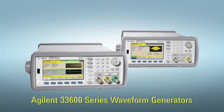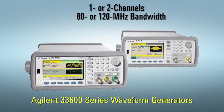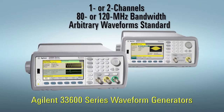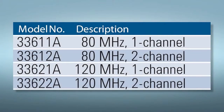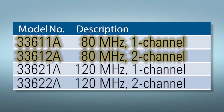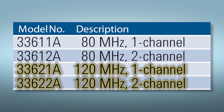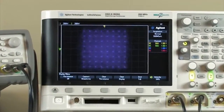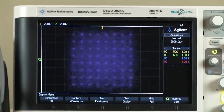The 33600 generators are available in 1 or 2 channel versions with 80 or 120 MHz output bandwidth. Arbitrary waveform capability is standard on all 4 models. You can get the performance level you need now, then upgrade your generator in the future from 80 MHz to 120 MHz if your bandwidth requirements change. 4 meg of memory is standard, but can also be upgraded to a full 64 meg of memory. There's even an optional IQ player available for the 2-channel models.